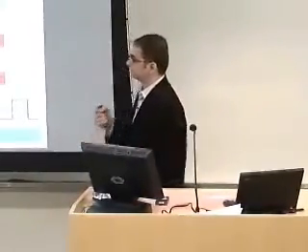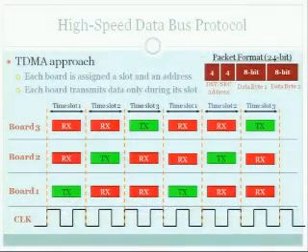Now, what happens is that this board can only communicate information when its slot is active. When its slot is not active, it will simply wait and listen for possible data. Now, the type of data we're actually sending on its time slot are 24 bits data because we're using a 24-bit bus. The first 8 bits are used for addressing. You can have unicast, broadcasting, and the rest 16 bits are the actual data.